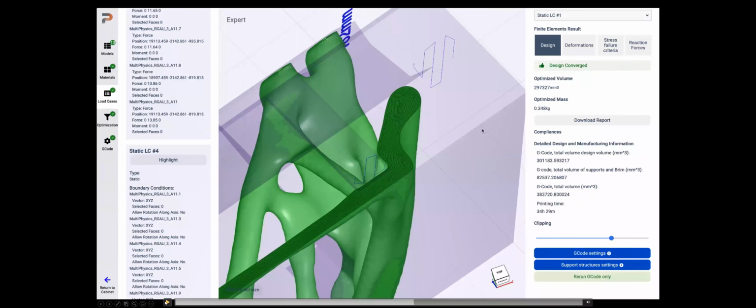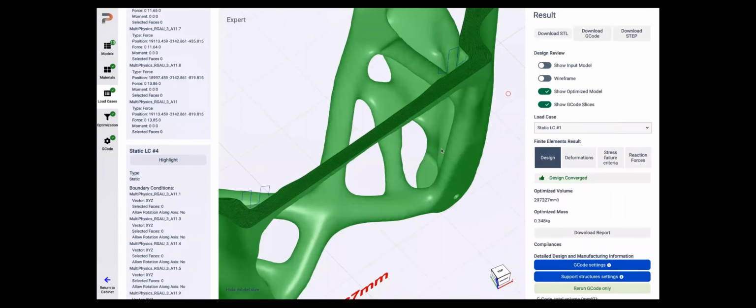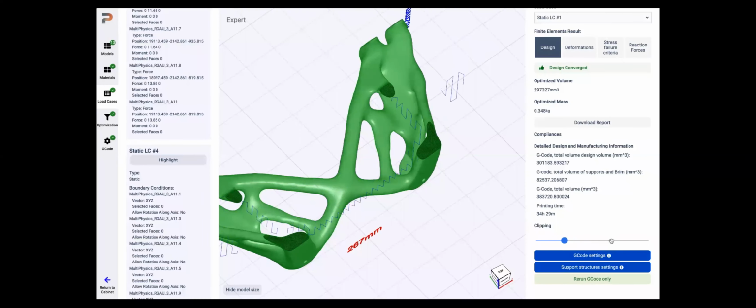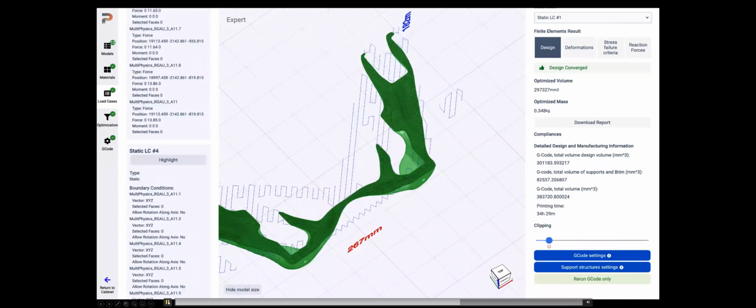And we solve this on the level of algorithms which generate the tool paths and calculate the extruded material, and the amount of extruded material in, let's say, areas where there is sharp curvature change, which is quite challenging.